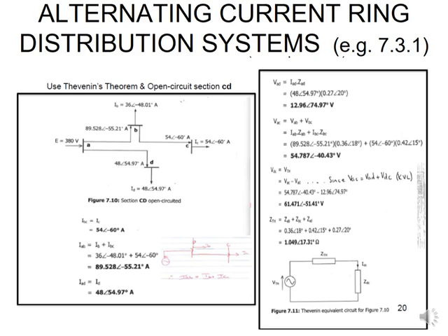Now, for us to work out our current IDC, where we're utilizing the Thevenin, we must remember that it's going to be that voltage, the Thevenin voltage, which was our VDC, divided by the ZTH plus the ZDC, which is your open circuit at the bottom. Because as they've drawn the circuit diagram, you can simply see there you've got VTH and then you have the ZDC coming in at the bottom as well.